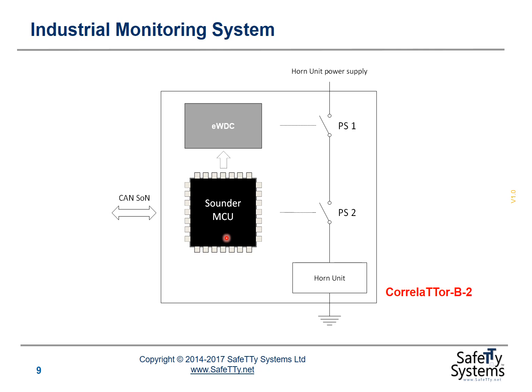For example, we'll have an internal monitor, an internal predictor, and an internal watchdog timer as part of the control software in this design. And we will use this controller based on commands that are received over this CAN link to the main controller module in the IMS.